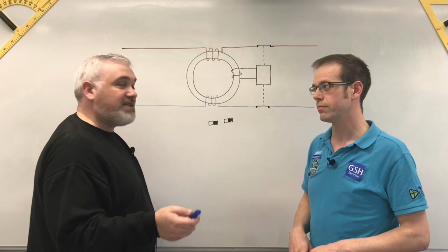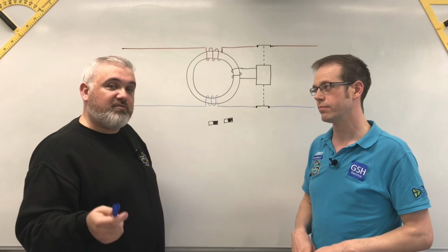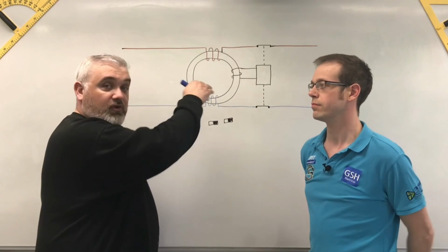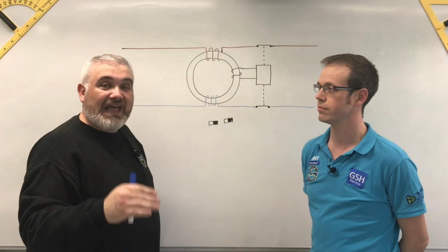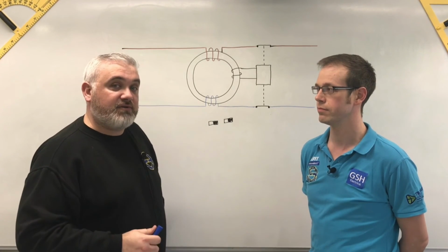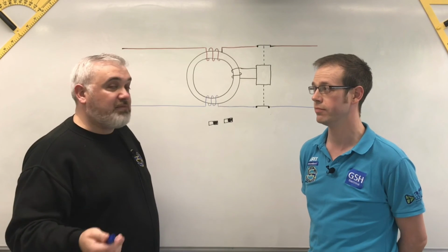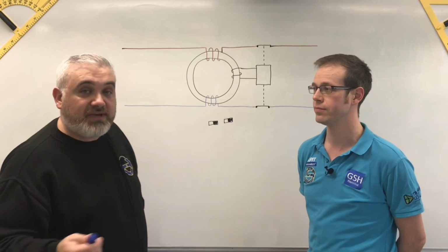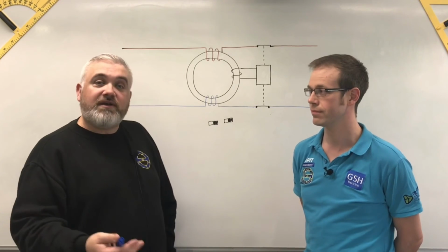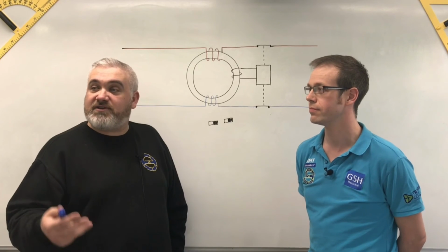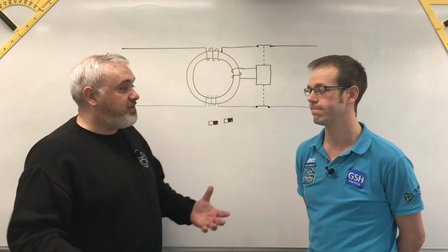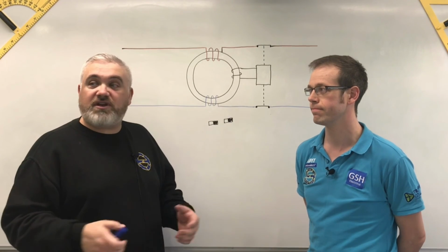So what that means is if you have devices which are saturated by DC, not only will the test button not see the shunt coil, but it will also delay and hinder the performance of the device to the British standard that it's made to, which is a problem. It happens a lot in industrial environments, but more domestic now because of the new technology we're bringing in. Hence BS 7671 introduced Type A, Type F, Type B. We now have to consider electromagnetics as an external influence in a far sterner light now.